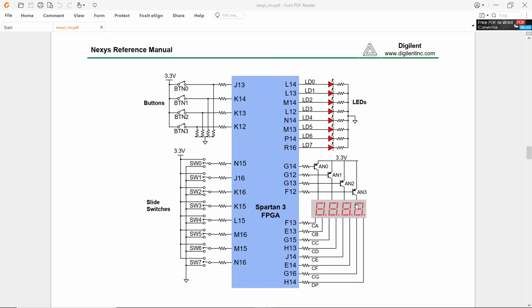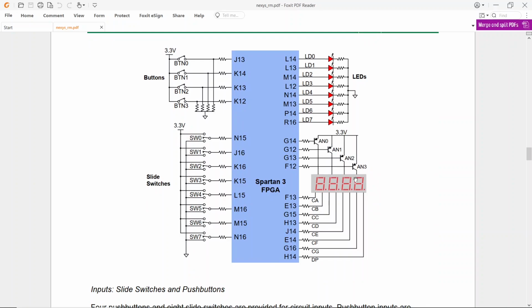So let's say if you want to display number 2, we will bring segments A, B active, and C will be inactive, or 1. It's like what I'm saying here: when we bring 0 to activate something, we're talking about negative logic. That may be helpful in the future in any other projects, or in electronics generally you can hear negative logic. So 2 will be corresponding to the segments A, B, D, E, and G. The rest stays ones, so it's inactive.